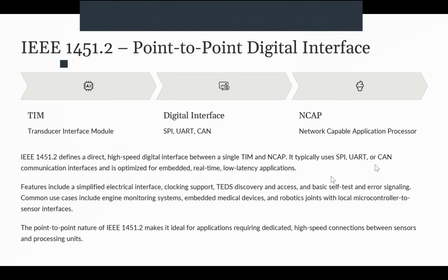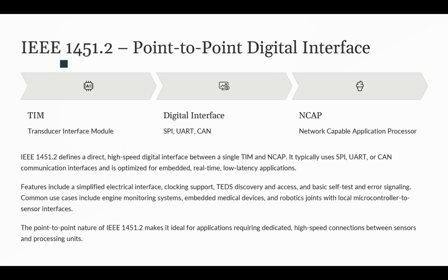Now, let's go deeper into some of the most important parts. One is Part 2, which is a point-to-point digital interface. As we said, this defines a point-to-point digital interface that connects one transducer interface module, one TIM, directly to one NCAP. Now, this type of interface uses fast and simple serial protocols, so it makes sure of reliable, low latency data transfer between a TIM and NCAP.